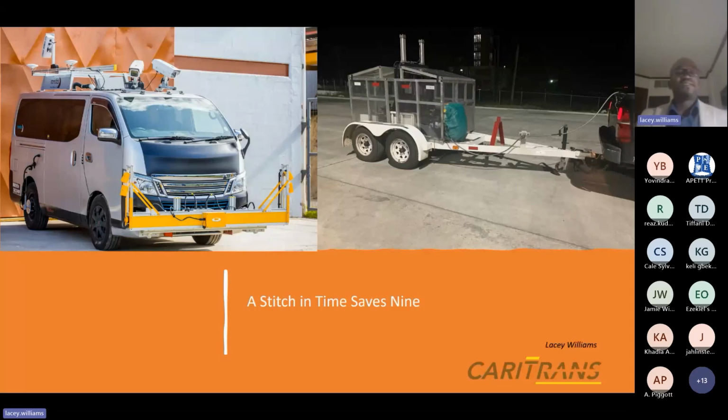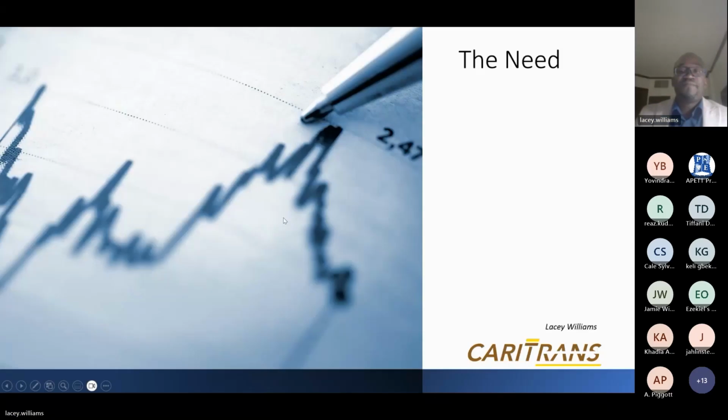The laser profilometer on the left, on the other hand, deals strictly with the surface. That bar you see across there has a number of lasers, and you'll see a bit more of a graphical description of the equipment in our subsequent slide. This is what is used to measure things like rutting, as you would have described previously.